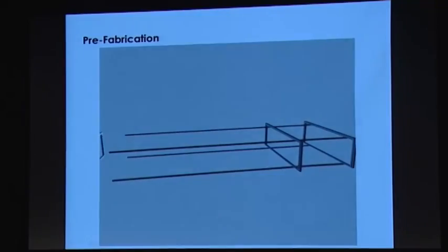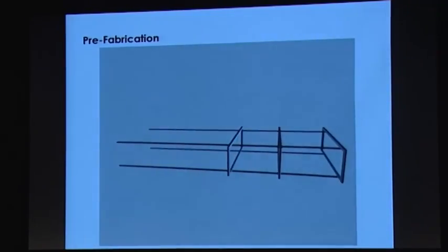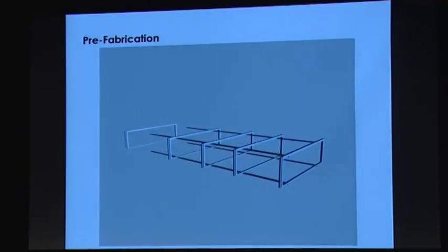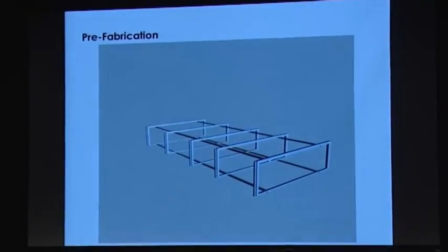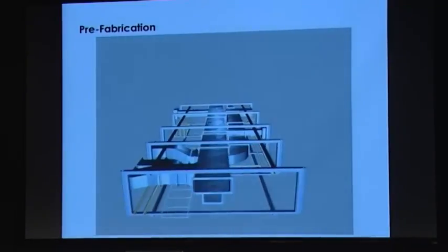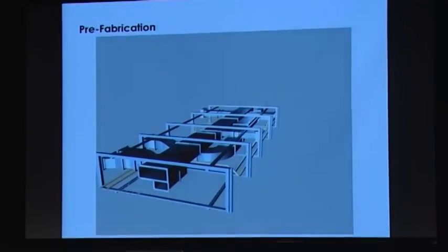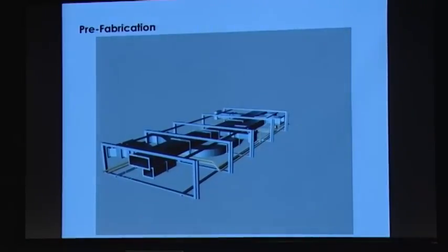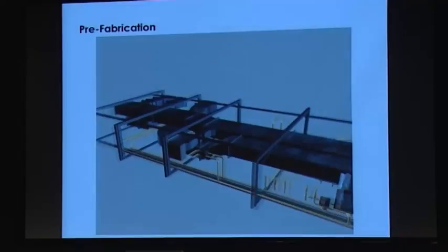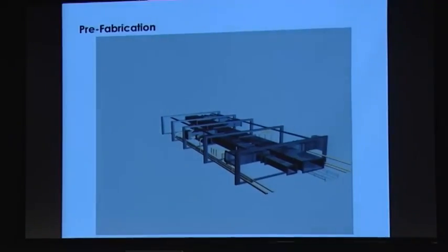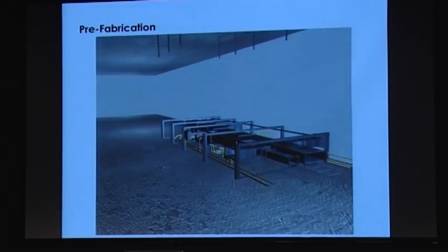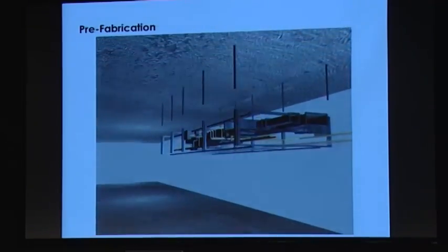I believe Michael Canistero has some stuff on prefabrication, but this is just a quick little video. This is done in the UK. Prefabrication, and from a contractor's perspective, that's it. Labor in the field is where your risk is, and prefabrication manages that risk better than any technology we've seen out there. So what you're looking at here is a rack that's been created, and the bill of materials comes directly for that rack. It's rack number 100, and the individual that's going to put the pipe on that goes to the cage. The guy hands him his fittings, and he puts it on the rack, grabs 101 and puts it on that rack. These are all pre-assembled.